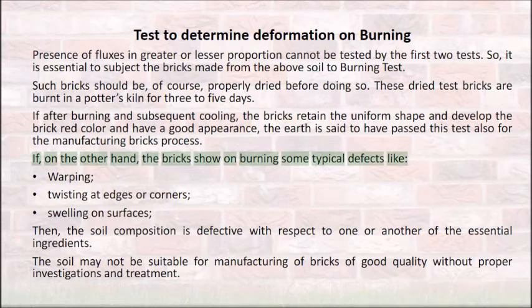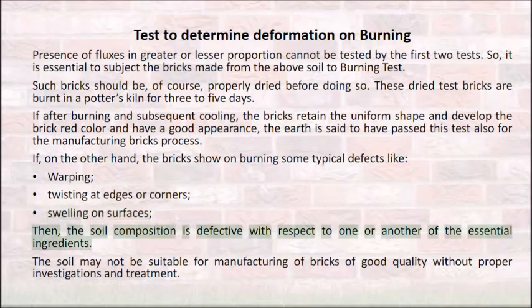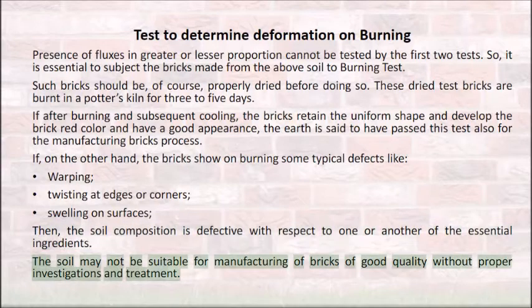If, on the other hand, the bricks show on burning some typical defects like warping, twisting at edges or corners, swelling on surfaces, then the soil composition is defective with respect to one or another of the essential ingredients. The soil may not be suitable for manufacturing of bricks of good quality without proper investigations and treatment.